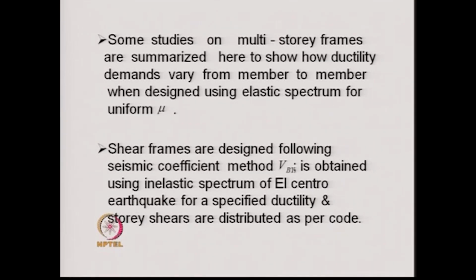Now, the masses for the frames are kept uniform all through, having a mass m at each floor. The yield base shear for the frames is calculated using the inelastic response spectrum of the El Centro earthquake corresponding to a specified ductility factor.